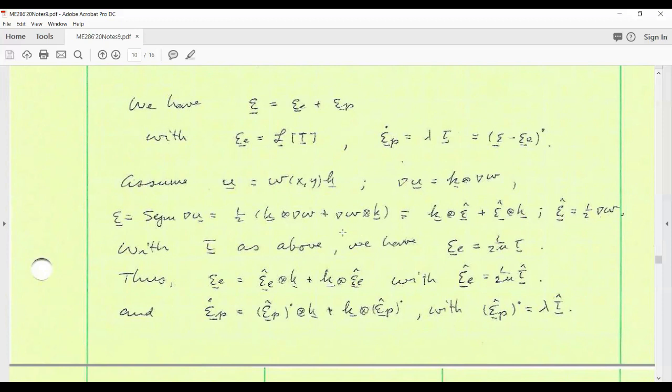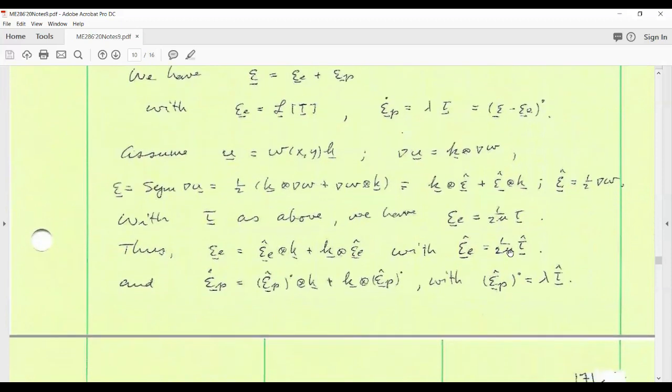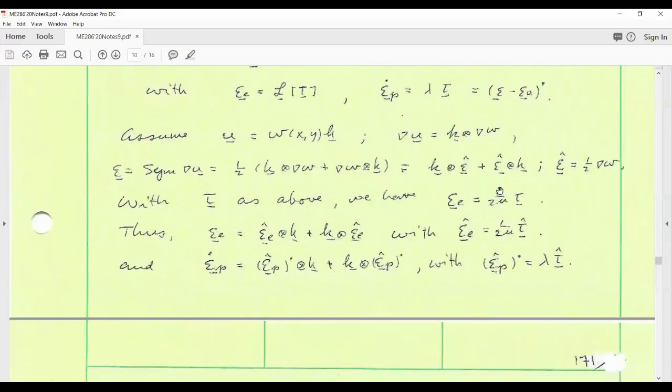Okay, let's see if we can use the tau that we had previously. Insert that in the elastic strain-stress relation. That tau is purely deviatoric, so the strain-stress relation will pick up only the deviatoric part of tau, which involves just the shear modulus.